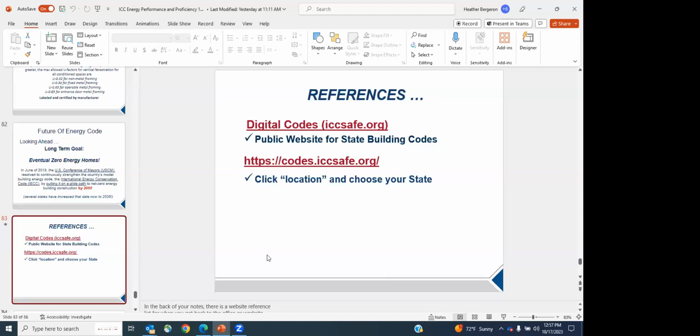The reason being is, I saw a study once where 60+% of all the windows in the United States that are being replaced today are being replaced with vinyl windows. And that's because vinyl is a product that doesn't use molecule to molecule transfer of heat, and so they're more energy efficient. However, aluminum uses molecule to molecule transfer of heat. And that's why Western, for example, uses what's called a thermal broken aluminum. That prevents the heat from transferring through to the inside. And so it becomes just as energy efficient, if not better than vinyl at that particular point.